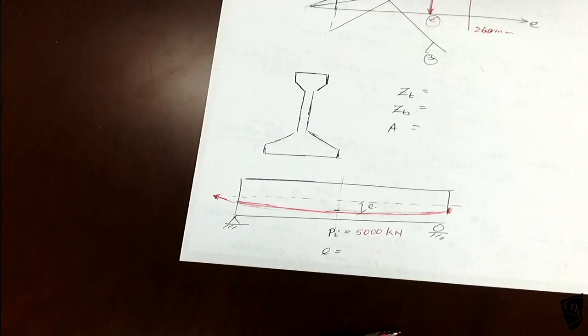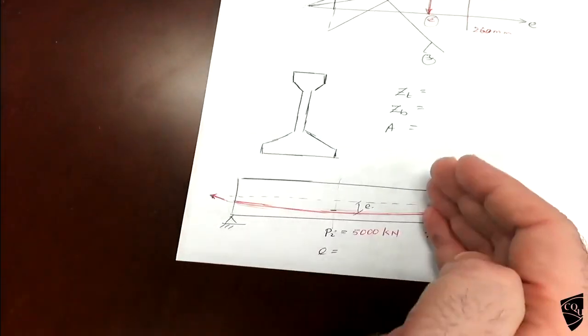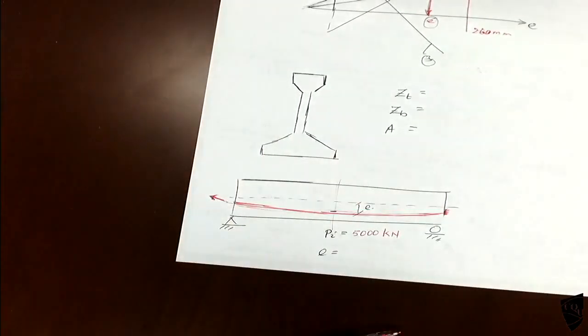If it is pre-tensioning, we just stretch the steel first and put the concrete. In that case, from here to there, same pre-stress. If it is pre-tension, it will be the same load from here to there.